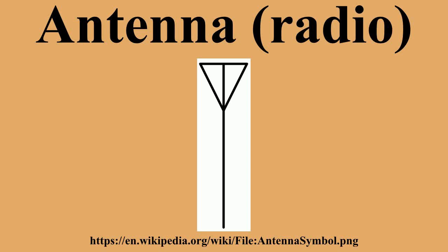An antenna coupling network is a passive network used for impedance matching in between the antenna and the transmitter or receiver. This may be used to improve the standing wave ratio in order to minimize losses in the transmission line and to present the transmitter or receiver with a standard resistive impedance that it expects to see for optimum operation.